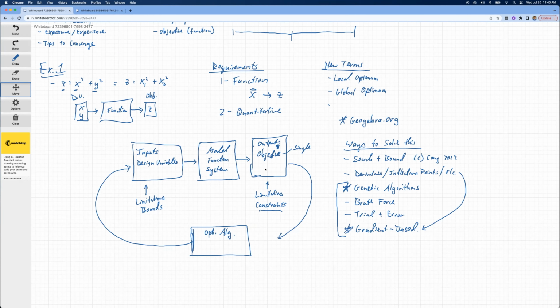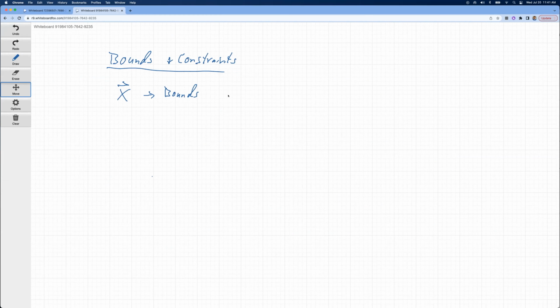And so that's something a little bit trickier to handle. And like Corey was saying, the SLSQP, GRG, a lot of these mainstream optimization algorithms can handle those types of constraints, and they're doing things throughout the process. They're computing gradients in those constraints, or in violation of those constraints, just like they're computing gradients of your objective function. And by the end, what they're saying is that we're going to satisfy all these constraints and minimize this objective. But during the process, we might walk out of bounds sometimes on these constraints at least. So I'm just going to say outputs, all outputs, there can be some constraints on those.